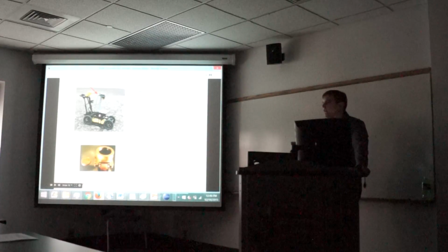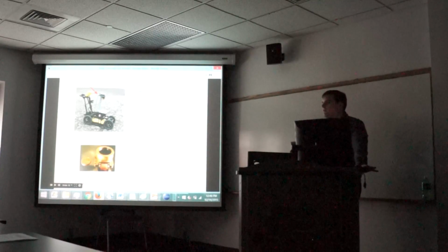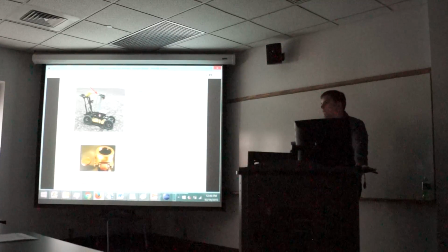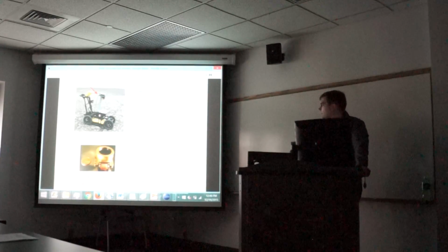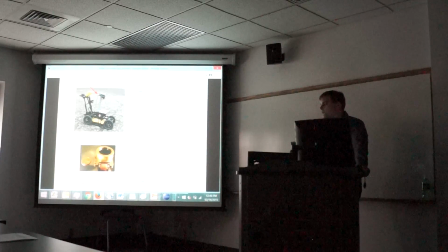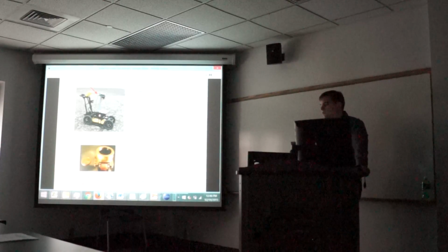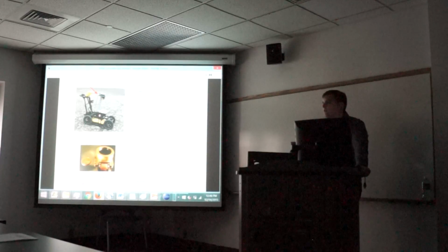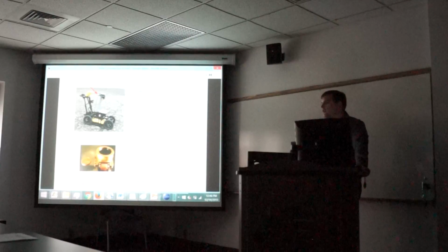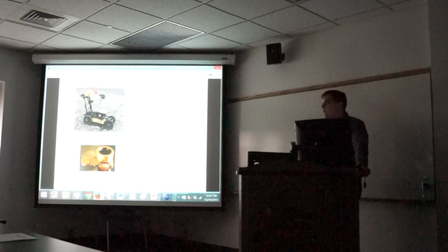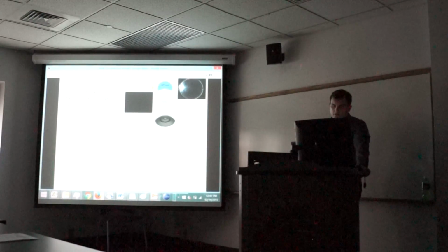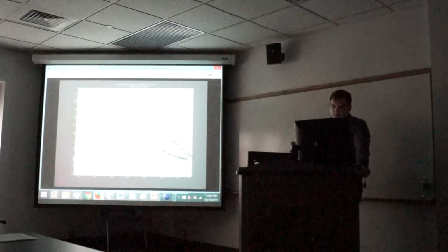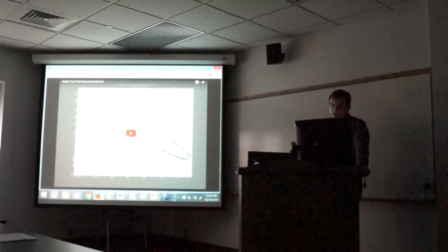A lot of it was areas that didn't have a lot of texture, so the visual odometry didn't measure the relative turn very accurately. So they benefited hugely from the solar compass in that respect. It would be interesting to see how much it could help with the driving that we did, because wheel slip and wheel stall was a significant issue, and the source for most of the error in that path reconstruction. If you watch the video, you can actually see a location where the path reconstruction pauses, but the ground truth keeps moving.